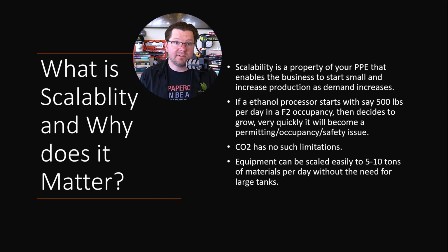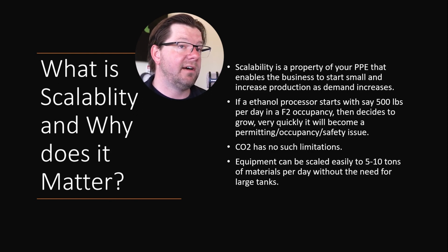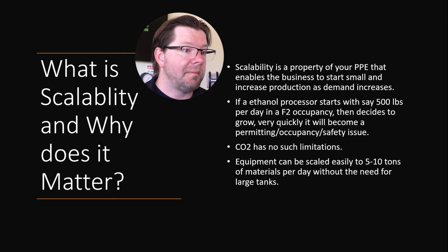A lot of the bulk CO2 is usually stored outside, and I know that a lot of people do that also with the ethanol that they have. So there are requirements for outdoor storage and indoor storage and how much you have in your facilities. Even the vessels, however, if you have a 1,000-liter vessel for your ethanol, you still have a significant amount of ethanol in your facility at all times. So that's something to be thinking about.